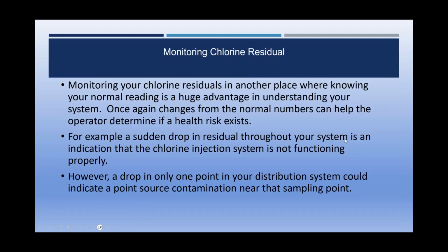So monitoring the residual in your system is also critically important. In the case I just mentioned, had someone been doing proper residual measuring, they would have discovered that problem as well. But in that case, they had different people monitoring the residual than was actually running the plant, and they were not communicating. So if you're running a system and you're getting residuals done throughout your system, it's important that you know as the operator what those residuals are,